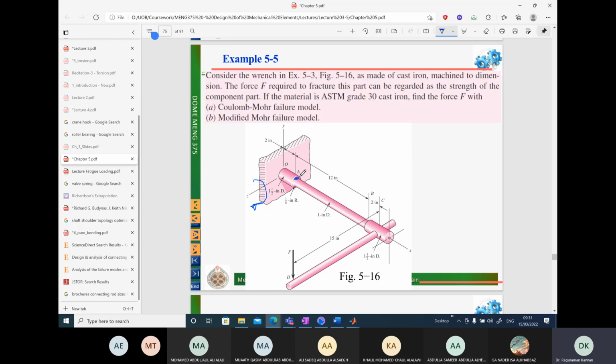If you consider that, that is subject to a tensile stress sigma xx. The compressive stress will be equal and opposite in the point on the bottom. What will be the shear stress component? Since we are looking at this particular surface here, the shear stress component is most probably going to be in the direction of z due to the torque.